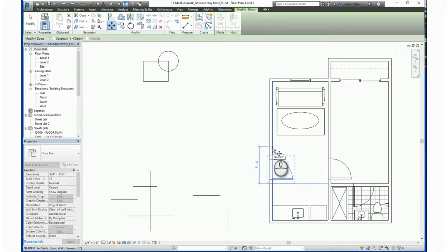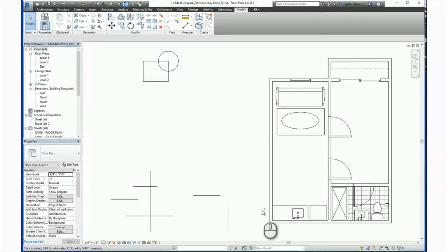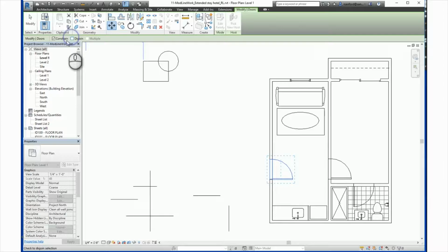And what I can now do is disjoin this door from this wall. So if I wanted to move this door over to this wall, select the first point, and I select the second point on a new wall, and it's moved. Again, I'll hit Ctrl Z. If I tried to move this with the Disjoin not selected, did the same 2 points, you can see here Revit will not allow me. The only place I can move is along the wall that is already hosted onto.